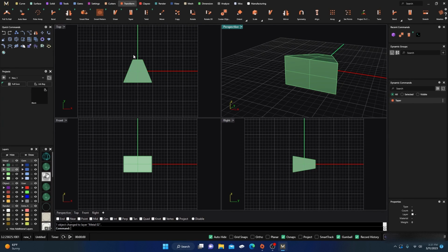Viewports, right? So right now, my perspective is activated. And this is important to know for when you're doing rendering, because you will need to have the viewport active for whatever render view you want. So if you want the right view, you need to click on the right one to make sure it's highlighted, and you can see the rest are dark, so they are not active. So if you do a render, it'll render from this side, right side here. If you click here and activate this one, it'll do perspective, and likewise with the others.